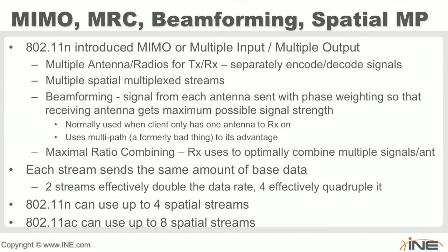He told me that. I received different RSSI values from the three different receptions of the wireless transmissions that I got from that client in response to something that I sent out. And now I'm going to use multipath to my advantage. I've got three different RSSI values, so I'm going to form this beam and send it out in these multiple different directions so that I can make the most out of the client's reception.